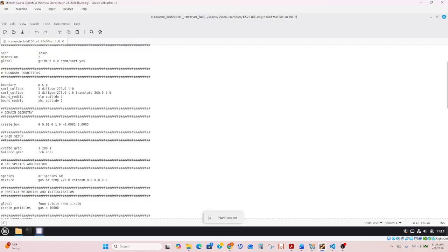And so here now we're going to define the domain geometry. This is basically defining the box that the simulation is taking place in. And here's where I picked the value for the dimensions of the cell width in the x direction. This is going to be one cell width because we're only going to do a quasi 1D problem.